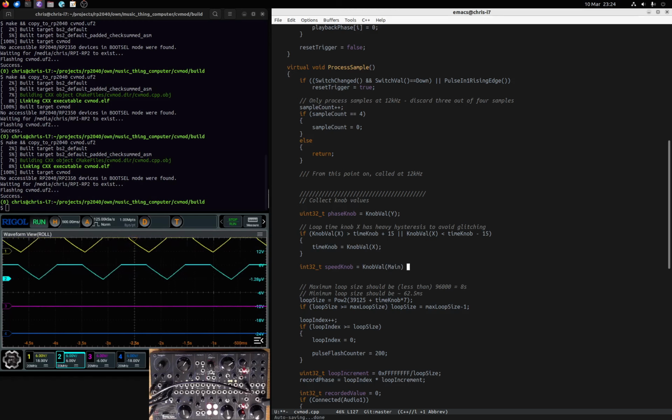But it seems like that is a sort of two distinct modes, one in which those playback heads are going at exactly the same speed, and then one in which they're going at different speeds. But what that means is we need some way of having a bipolar control for the speed that goes through 0, but that 0 is a value we want to be able to hit exactly.